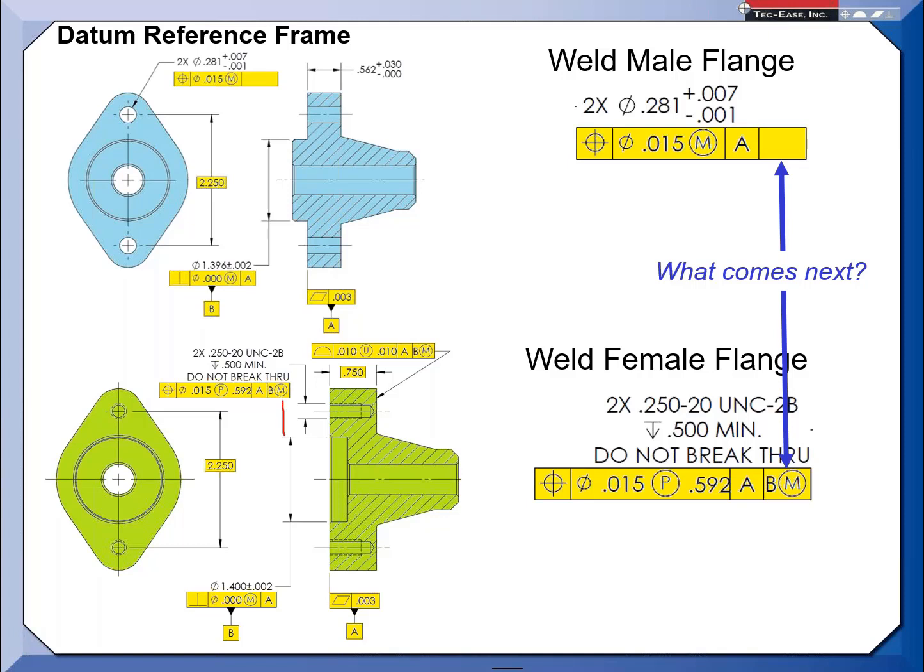FYI, when engineering does this, they put these M's on here. The downside is the part can now shift and move. By allowing these 2 mating parts to come together, this flange could come over here and shift, in other words, offset. That may not be good in the design because I had a wall over here. This part just shifted. So when you start doing the shift, features are going to move, and engineering has to take that into consideration. You're allowing more possible assembly shift, and that would be a design concern engineering would have to pay attention to.